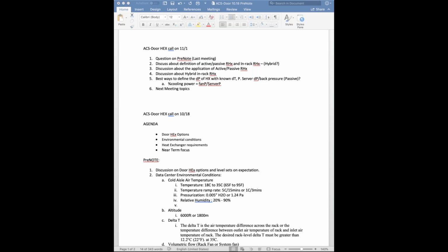So with the TAC Frontera deal in Texas, that solution is going to include a hybrid. So it's going to include direct liquid cooling for the chips and a rear door, an active rear door, so that chilled water is supplied to the row-based CDUs. And then the row-based CDU is controlling, obviously, the temperature to a bank of racks. That chilled water is going into the rear door first, so it's neutralizing the heat load in the outgoing air from the servers.